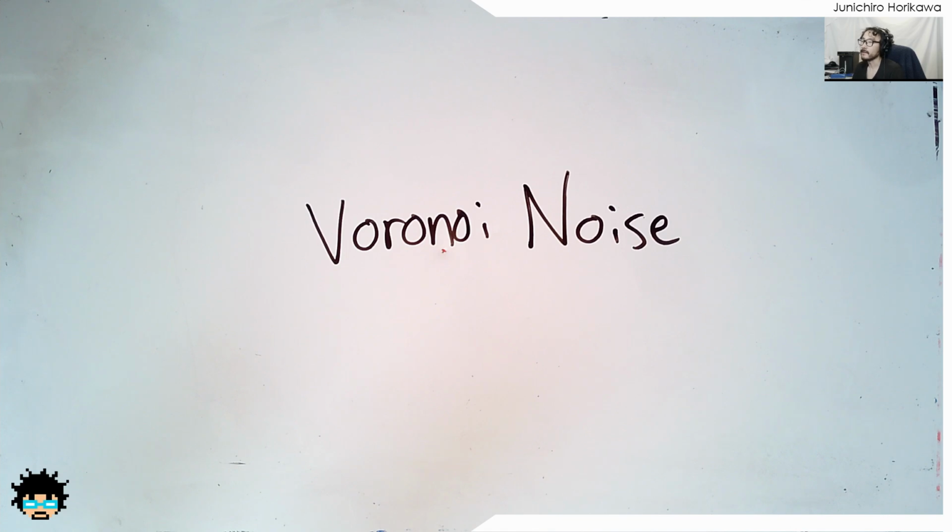So it's a bit hard to create an ocean-like surface with this Voronoi noise, but instead you can have a bit more analytical information in terms of Voronoi using the Voronoi algorithm. So the value that you're going to retrieve out of this Voronoi noise is pretty much the same as the Worley noise. I'm not going to explain the basic algorithm for this one. Instead, I'm just going to show you how you can use it in Houdini as a parameter set or as a function, and use some of the Voronoi noise specific values for some purpose.